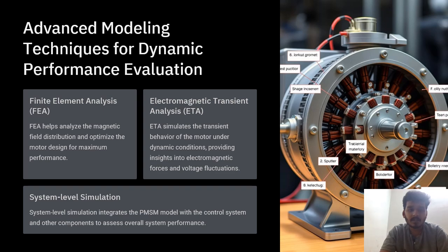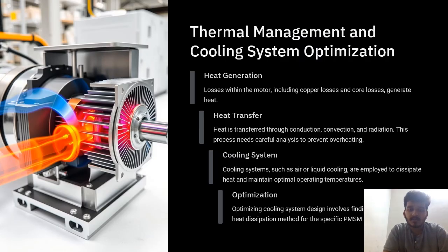So, in these different scenarios, thermal management and cooling system optimization. Why is thermal management important? Thermal means heat generation. Losses within the motor, including copper losses and core losses, generate heat. Copper losses depend on the current, and core losses depend on the voltage.